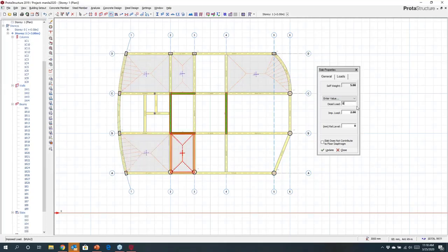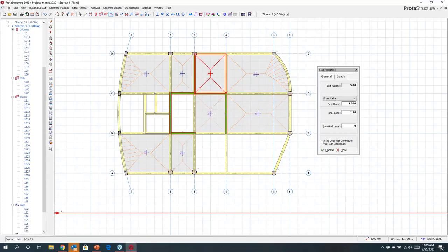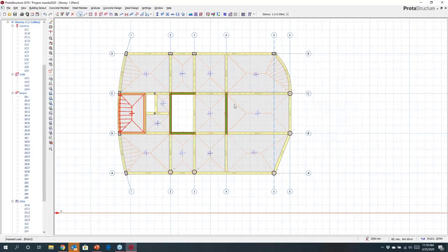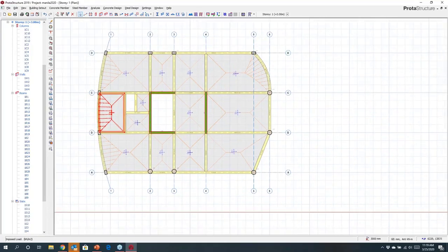Okay, now you can put in different loads here. You can just type them in. So maybe I've got a slightly lower live load, or maybe my live load's more. Okay, we can just come in and create these to suit the underlying loading. Okay. Now, before you get too far in the model, you can check things.